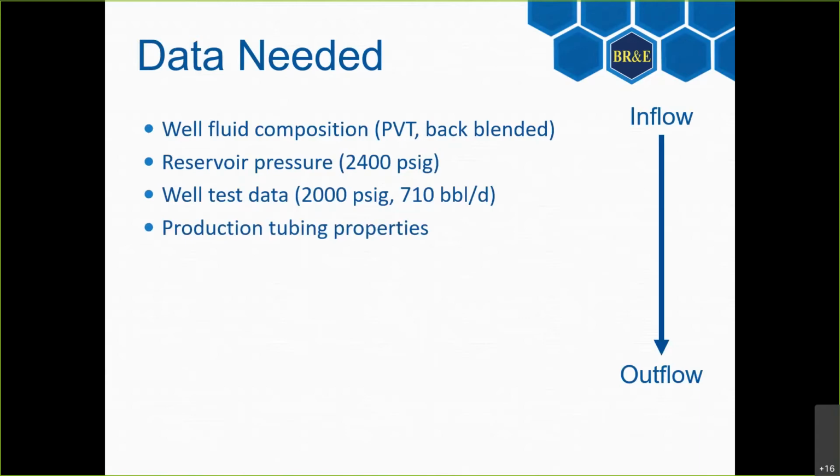when that oil got up to the initial separator, how much it was oil versus gas. It's looking at the actual flow rate going into that node, and most of the time going into that node, it's either mostly all oil or all 100% oil going into the well face. But either way, we're looking at the overall flow rate of the hydrocarbon, whether it's gas or oil, is what that flow rate is. From there, we do need to know the properties of the production tubing, so the size, the length, obviously, if there is some angle to it, what the angles are. If you have a deviation survey, is what that typically will outline. We can take that and use that to define the production tubing.